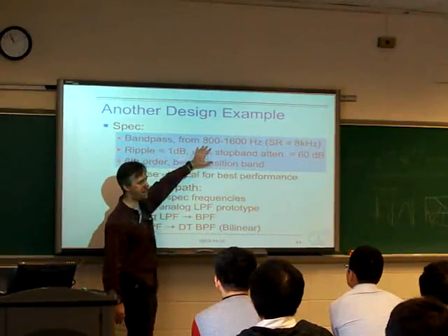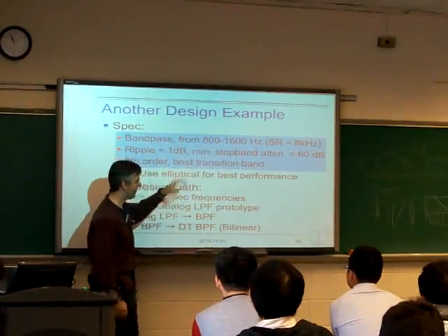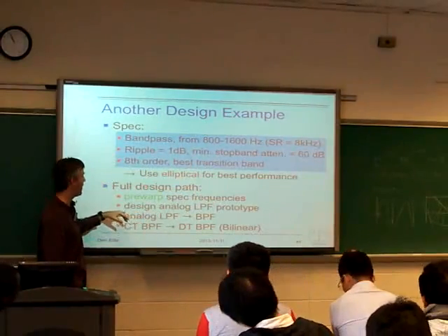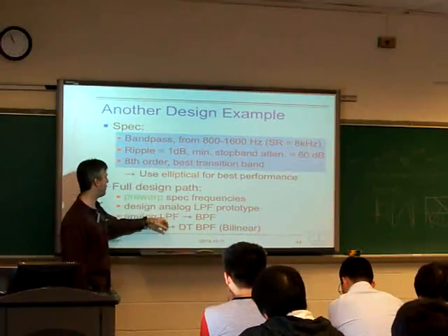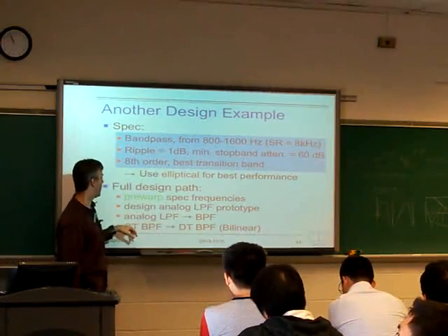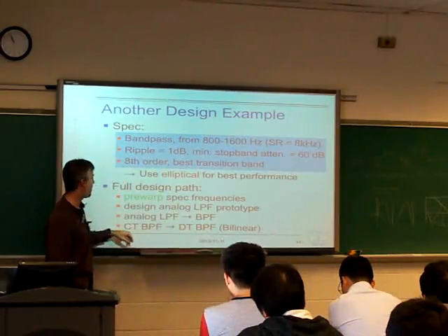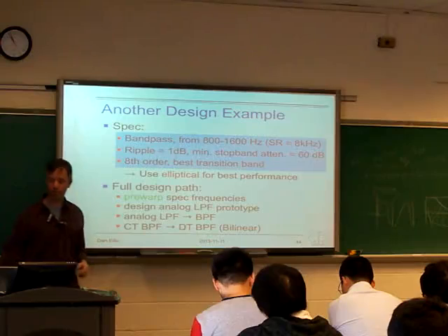It's complicated, but we could presumably do it. Then we take that, generate the analog bandpass filter, and then map it to the discrete time using the bilinear transform.